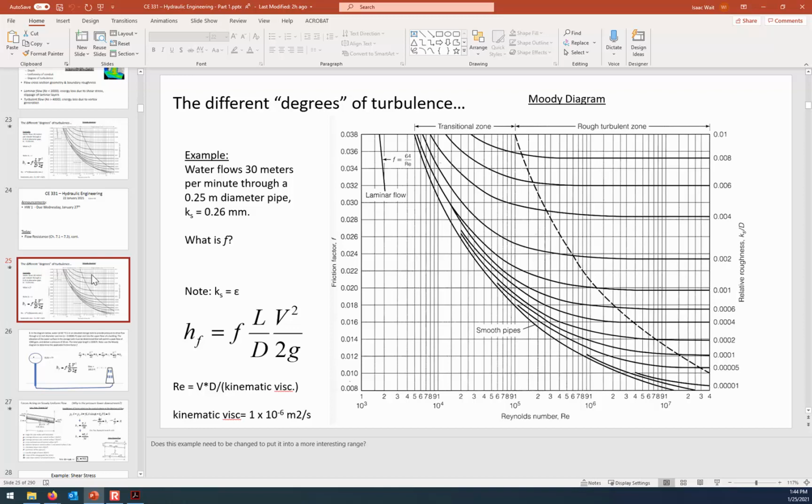I've never actually considered this one before, so we're on new ground, but what is the Reynolds number in this case? Remember, Reynolds number is velocity times diameter divided by kinematic viscosity. So let's calculate it here. The velocity of flow we calculated earlier was 4.07 meters per second.